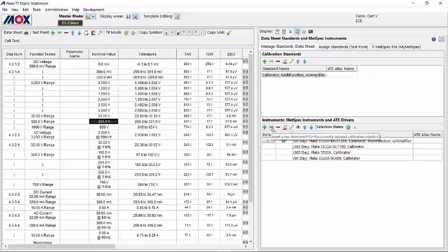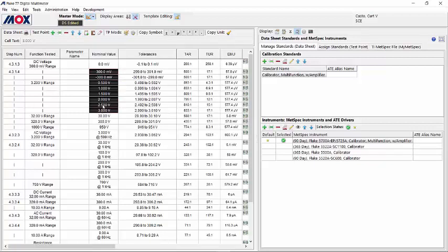This is the insert button, which is just like add, except it inserts at the current location. Delete. This will delete the currently selected item, or if supported, items. And this is another thing I want to talk about in MPS. A lot of features that are in here, you can multiple select. So for instance, if I first click on a test point over here, and if I hold down the shift key and click on this test point, it will select that range. So for instance, if I tell it to delete these test points, okay, that will delete the selected range. If I only have one selected, then obviously it will just delete the one.